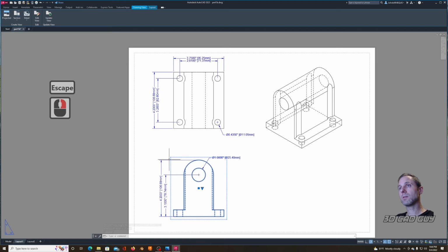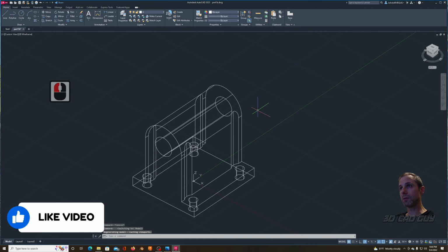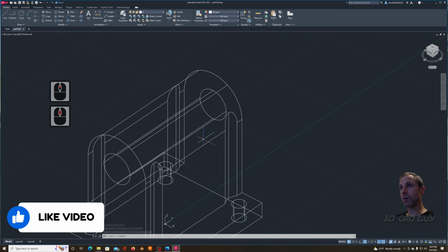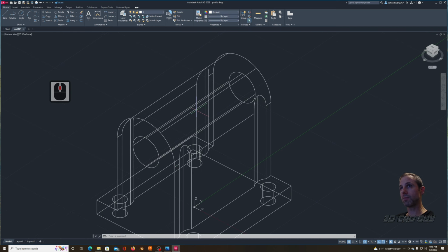What's cool as well is if you want to modify this after the fact, you've already done this work. Normally in 2D, you'd have to redraw it if you were going to do some heavy modifications. But in 3D, we don't generally have to deal with that. And we still need the holes that go into the sides. We've got to drill a few holes to be able to lock down on this in this bore area. I'll start out here.